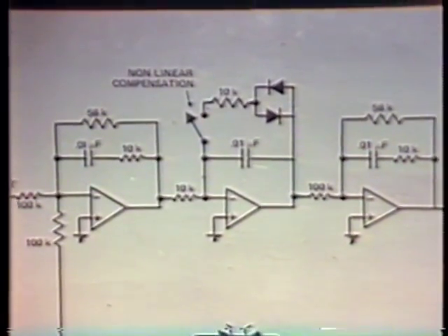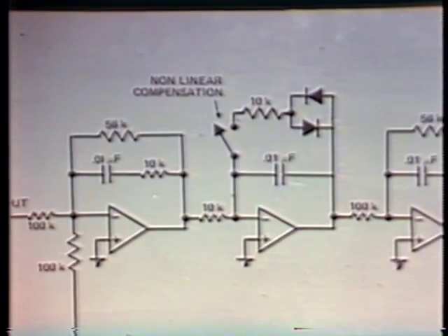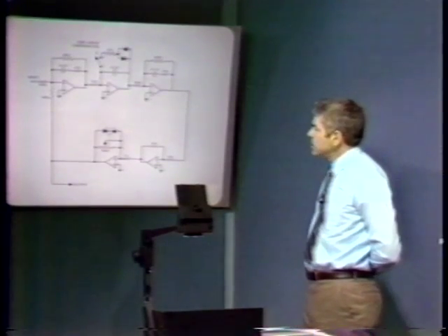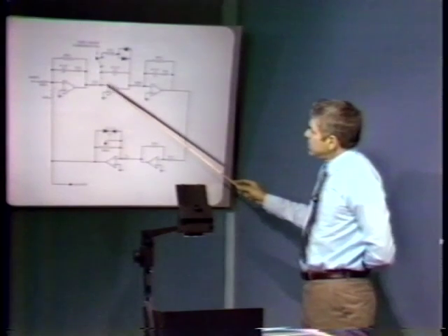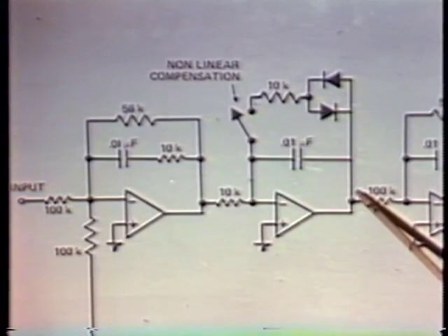What you do, I think, or at least one technique for compensating this sort of a system, is to consider what happens. If we keep track of signal levels, we find out that when the system is behaving normally, at least in the high gain configuration, we normally want to cross over in this system above 950 hertz. When the system is behaving in that manner, the signal level here is very, very small.